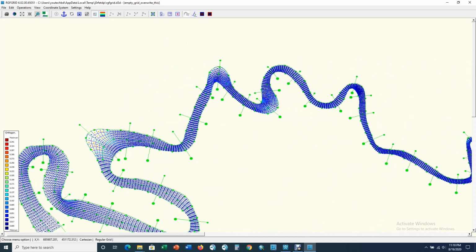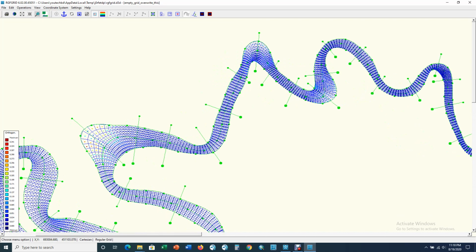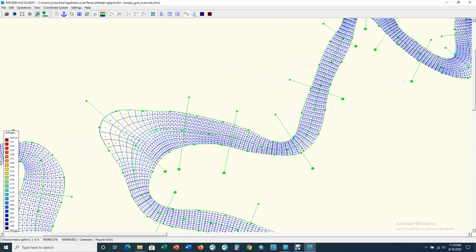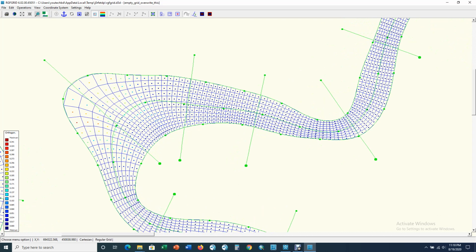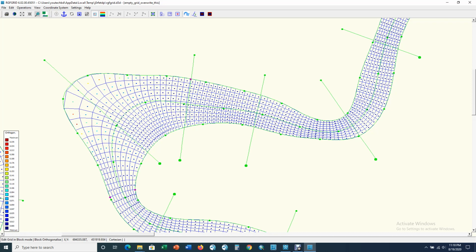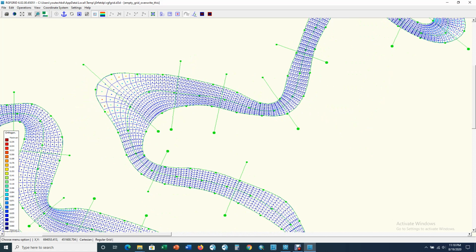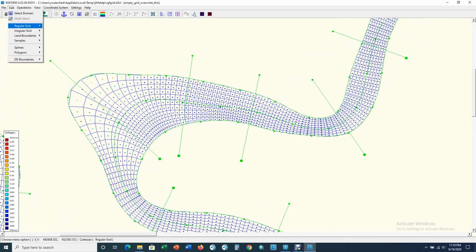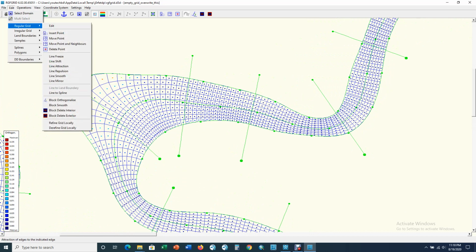So let's move on to the other place. This is another place where you have a very rough orthogonality, so it's much higher, 0.341, so we have to correct it. To do that, at first you do some block orthogonalization. So let's do it from here. You have to do it on file level only, and it will work. When you have quite a lot of experience, you will get it right anyway. So now we'll do some smoothing.